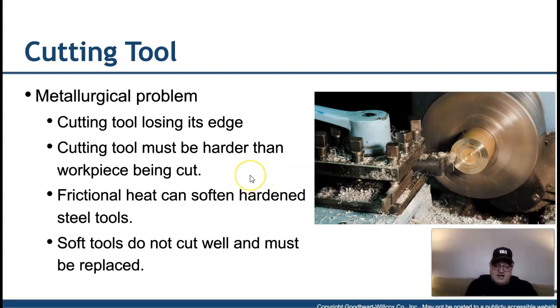Of course, in today's manufacturing world, oftentimes we're pretty much using inserts and just changing those inserts out. When I was an apprentice, we sharpened a lot of tool bits. There is still a small niche area for that, and there's still a market, especially for custom form ground tooling, but it's not quite as much as it used to be, because of the insert technology that's there today, and again the wider range of different types of materials there as well to give us better cutting tools.